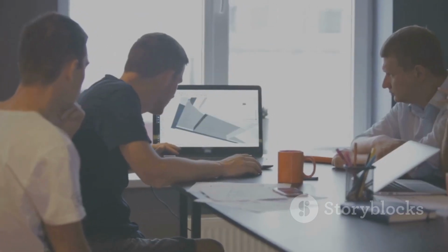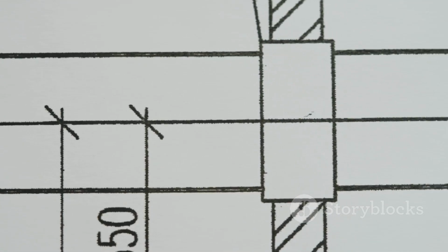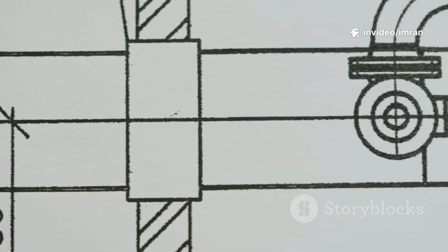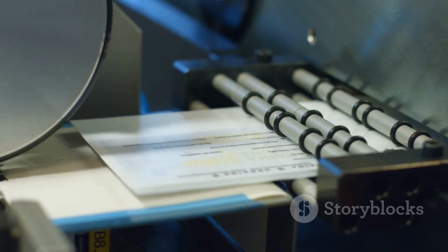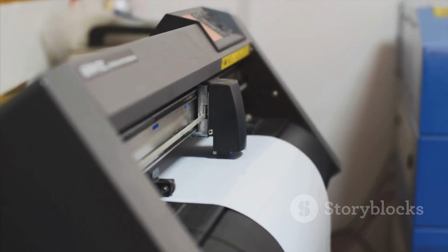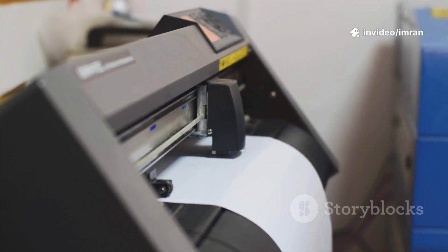Exporting is crucial for communication and collaboration. Many AutoCAD designs are printed for construction or client meetings. Printing, traditionally called plotting, uses the Plot command, accessible via the printer icon, Ctrl+P, or the command line. The Plot dialog box controls printing settings. Select your printer or a DWG to PDF plotter.